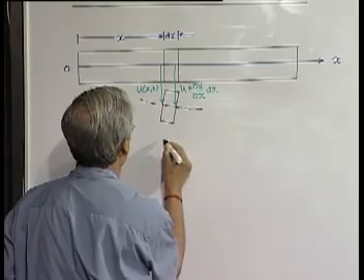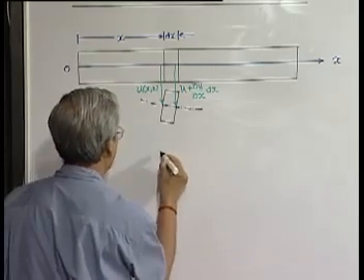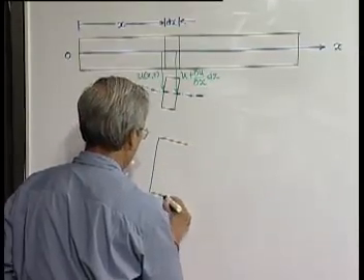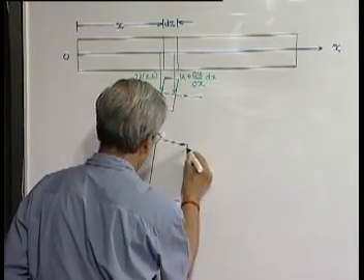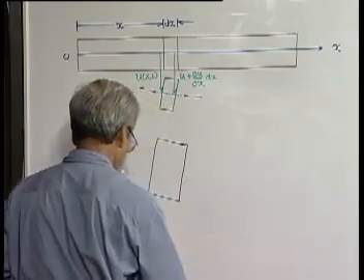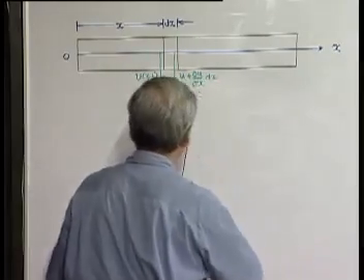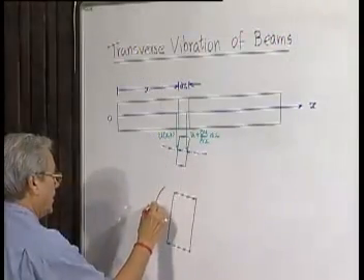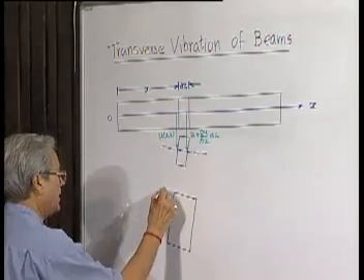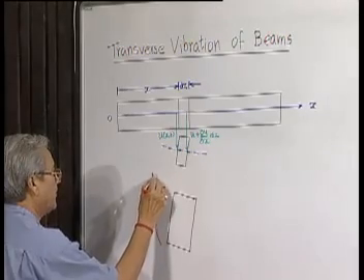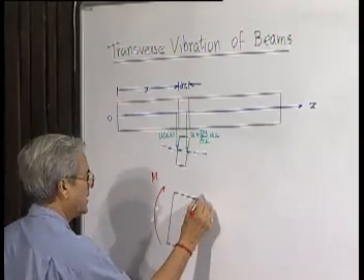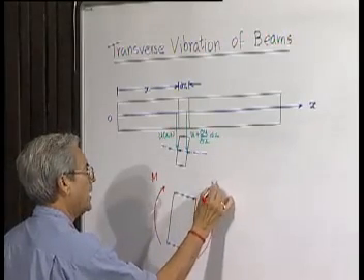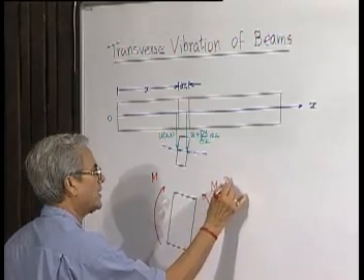Now if we consider the free body diagram of this element, the two ends, now when a beam bends like this, the moment acting here will be M, a bending moment, this is not a twisting moment, this is a bending moment. The bending moment at the other end will be the same M plus a little different from this.